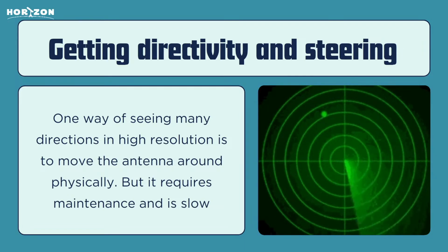So this is a good method as it accomplishes what we want to do. But the problem is the refresh rate, knowing how fast the object is coming or how frequently we can get that data, is very slow, because there's a physical limitation to how fast we can rotate a huge, highly directive antenna. And again, using motors and controls for the motors and having all those moving parts may become cumbersome. They require maintenance, and they're highly expensive sometimes. They need to be very precise in a lot of cases, and so these all give a lot of constraints to this method of localizing objects.